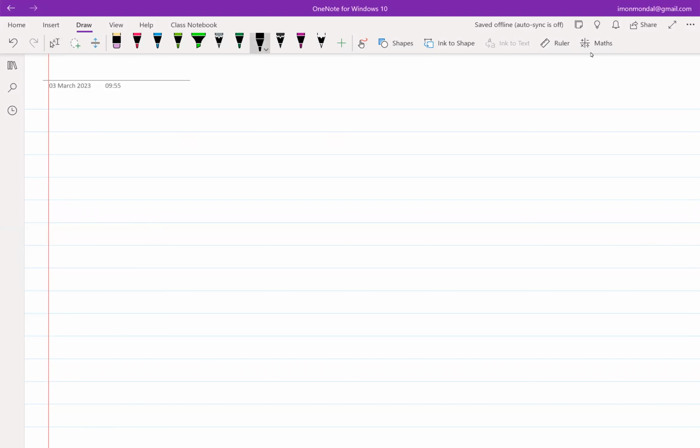Okay, so good morning and welcome back. We were discussing one particular configuration of biasing a MOSFET by taking current out of the source, and we came to the conclusion that this particular architecture auto biases itself, and then we delved further into it.